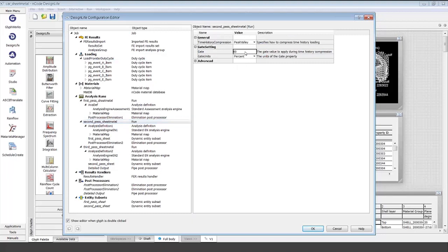What that means is the time series data being squiggly, it's going to remove non-turning points, and even further, it's going to remove a lot of cycles, which you may say, hey, hang on, time out. If you're removing a bunch of cycles, then non-conservatively, we could be removing a lot of damage. And that's fine, because all we're going to use this pass for is to find hot spots, not of stress. We've already done that. We're finding a further reduced set of hot spots of high fatigue damage, a quick approximation using this very aggressive peak valley gating technique.